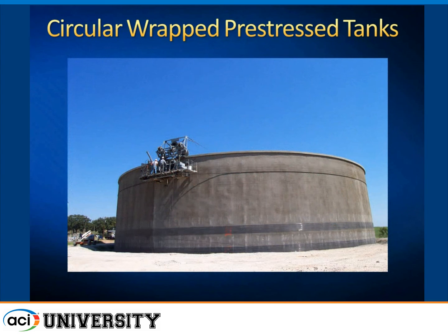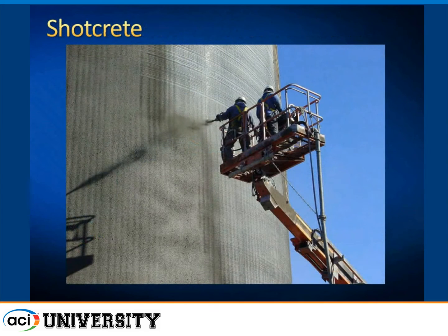And here's wrap pre-stressing. You basically take a high-strength wire, you attach it, and then you pull it under tension around and around and around, laying it in place. And that way you eliminate some of the friction forces. So it's different than the pre-stressing that you see in 318 or 301, the specification for that comes as a result of following 318. And here's Shotcrete.